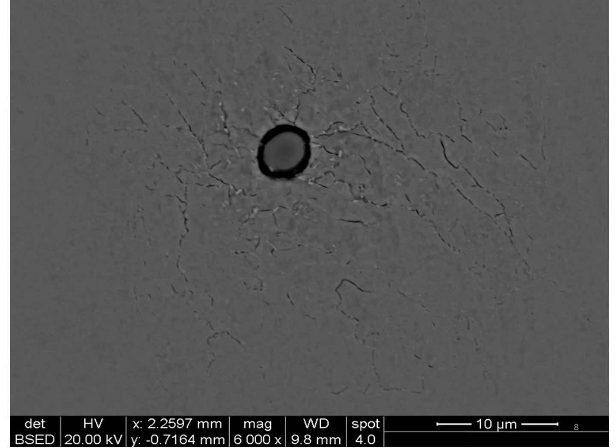Here we have a better view of subfigure C from the previous slide, and we can see at the centre an intact particle with no apparent internal cracking, which has decohered from the surrounding matrix. But in doing so, it appears to have created a field or a cloud of many sharp crack tips. So I'll trace around the outer edge. Note that this is far, far larger than the parent particle and appears to have a preferential direction, but there are still crack tips, or what appear to be crack tips, going out in many different directions.